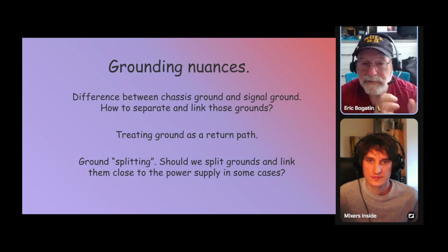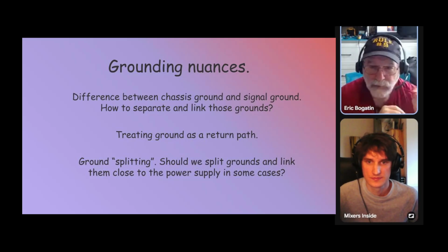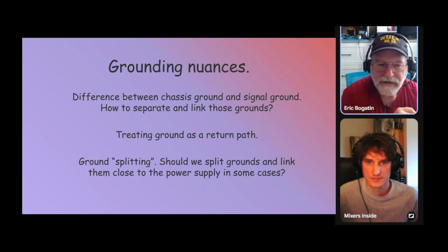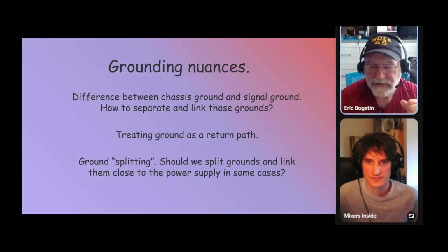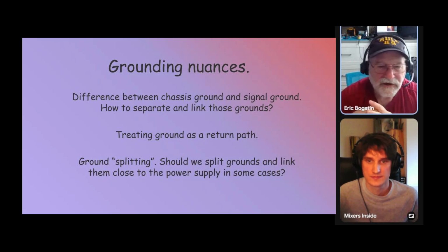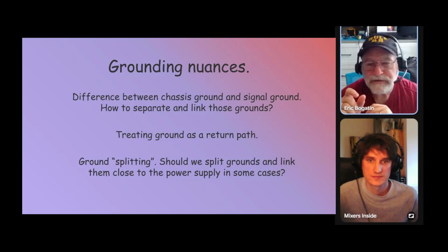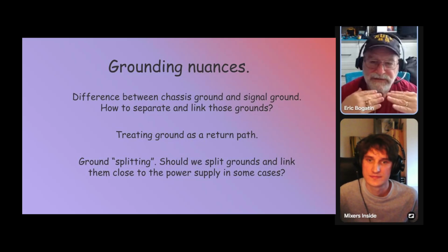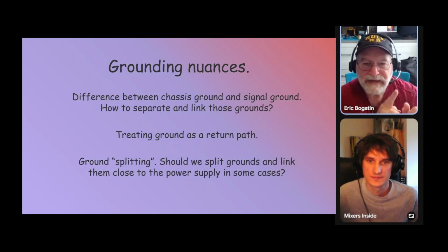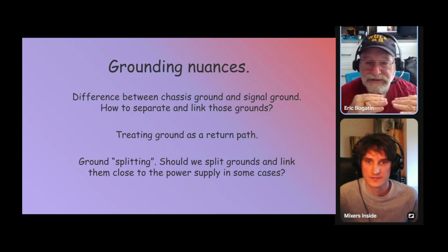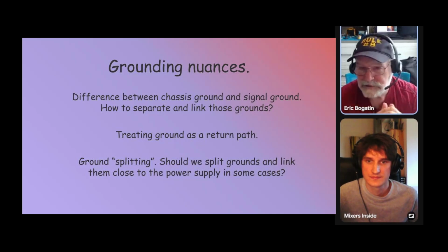And that way, in the schematic, you can identify, hey, this is a really sensitive reference line that I want a different net than the ground net that's used for all the returns. And even though it's going to be ground, the component that you add is a 0 ohm resistor, and you can just place that 0 ohm resistor on the board. It has no impact on the signal. Or if you know, okay, that's what I'm doing here, you could take it out and just put a short across it and not put the 0 ohm resistor there. But it's a way of tricking the layout software into thinking about that isolated return that is now protected, so I have no current flowing in it, no voltage drop across it.